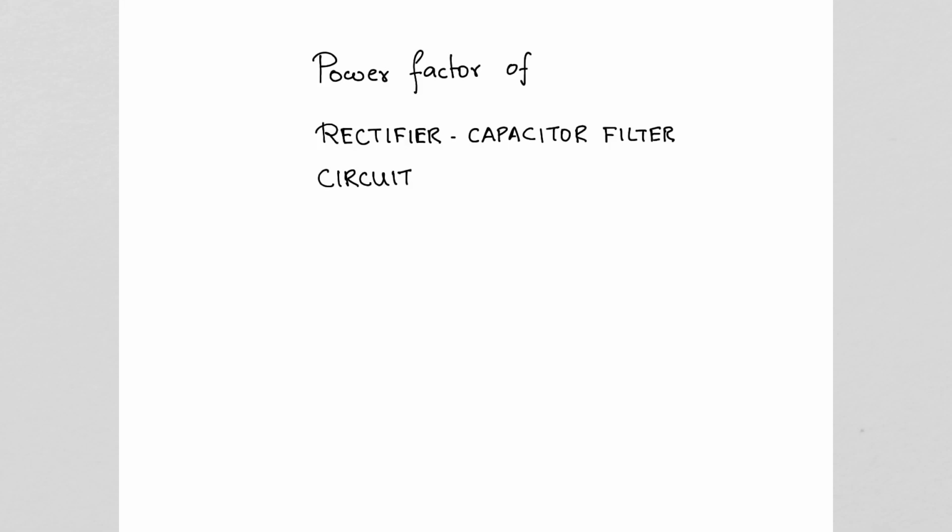Let us now find the power factor of a rectifier capacitor filter circuit, only by using the measured voltage and current wave shapes on an oscilloscope.